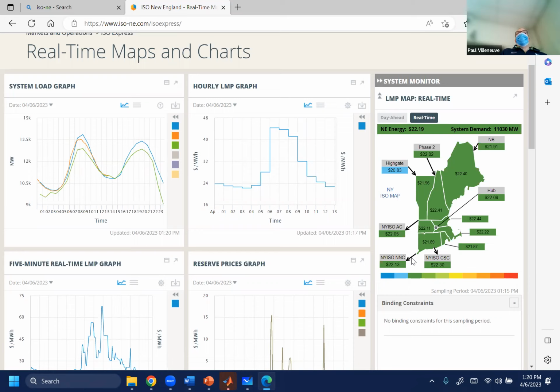You don't make money on these projects because they are cheap to build. It's that they have no fuel costs. Once a solar field is running, it's very expensive to build. If you look at the cost per megawatt hour, I mean, you need about 4 acres of land to get 1 megawatt. So you need a fair amount of land. You could put up Maine Independence Station on maybe 4 or 5 acres, and that's 550 megawatts. An equivalent solar farm is going to be, I don't know, 5,000 acres or 4,000 acres to produce that. This takes up a huge amount of land.